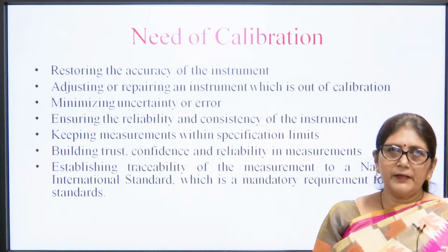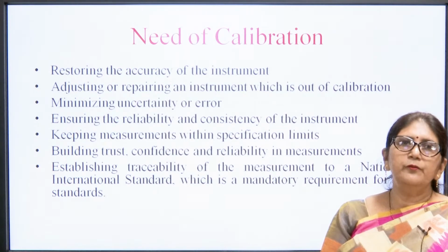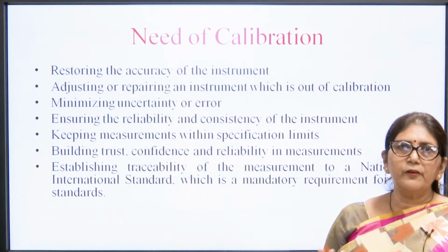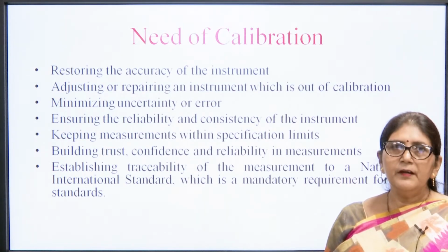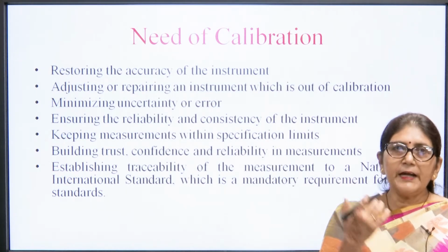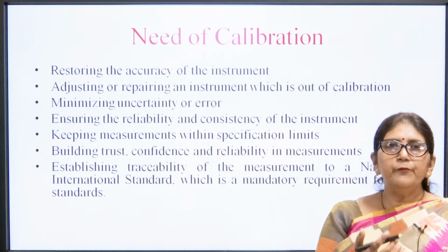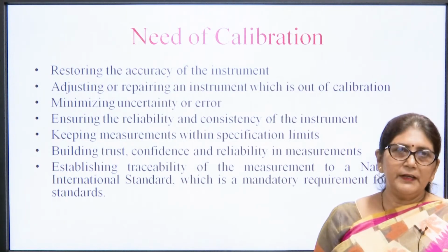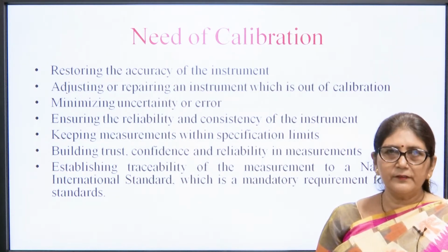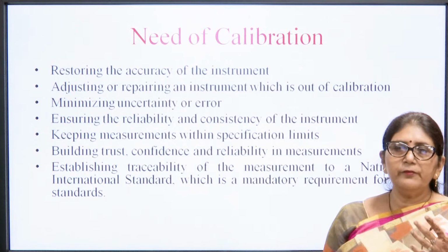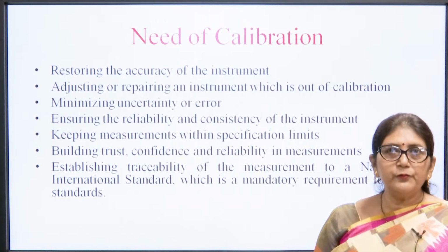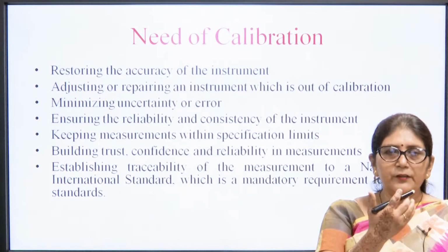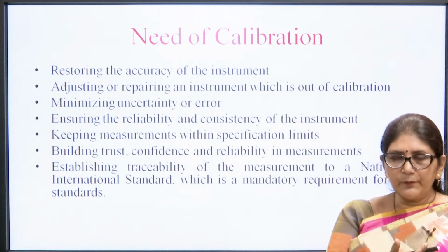And by calibrating our instrument we build trust, confidence and reliability. And generally, through calibration we basically establish traceability with the national or international standards, because ultimately we are comparing our instrument with the instrument that is kept at the national standard laboratory.